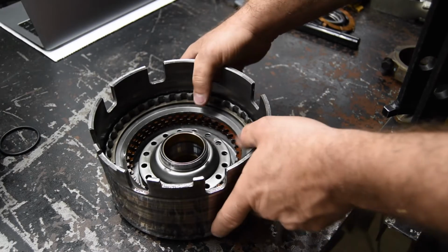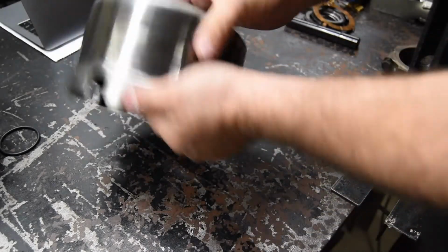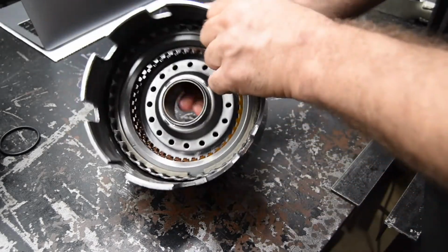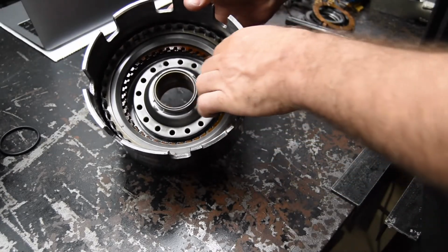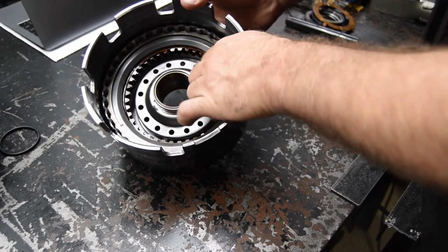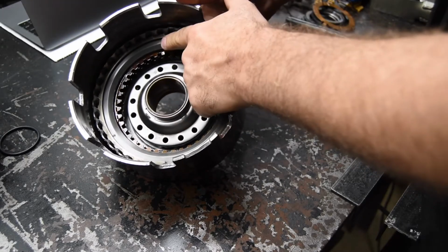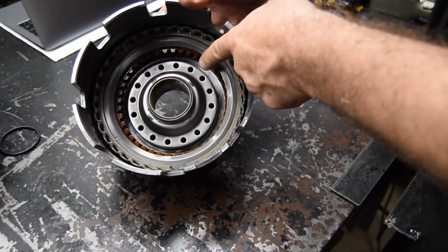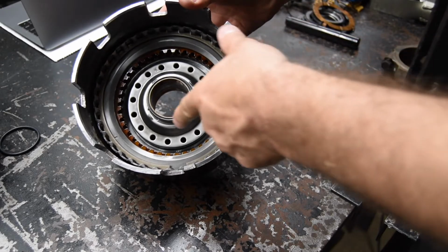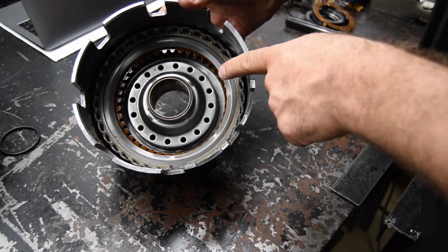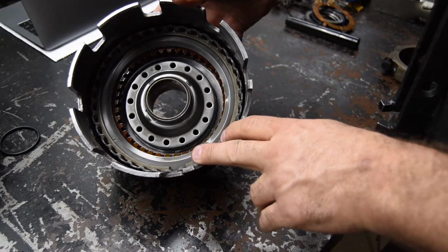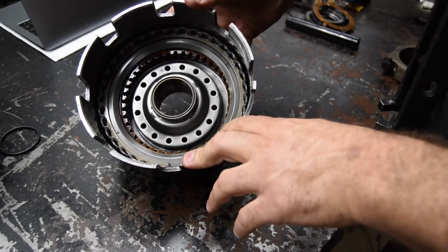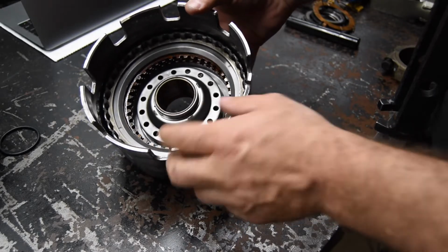Here we are at the table. We have the clutch out of our transmission, the 4L60, and this is the reverse input clutch, and you can see it's still fully assembled. Inside it we have the clutches. There's also the steels. Of course, the top is the pressure plate. There's our return spring plate, which with all those holes, those are where the springs are located. All the parallel spring pack is located underneath there. And then down below that is the piston, and of course it's got the piston seals on it.